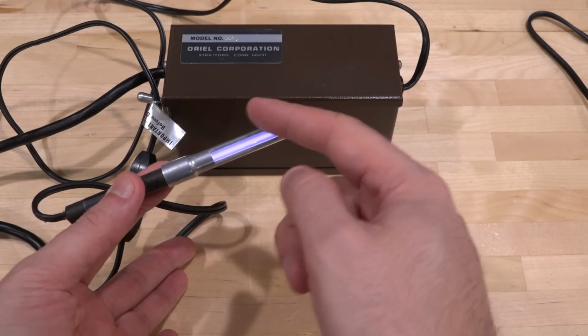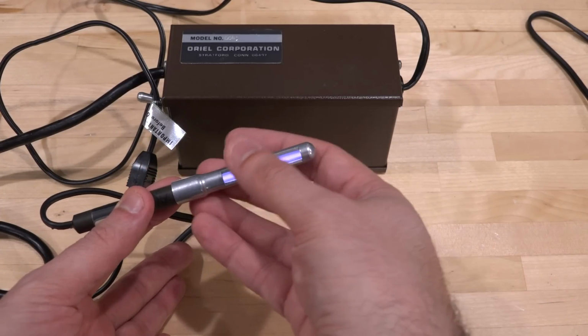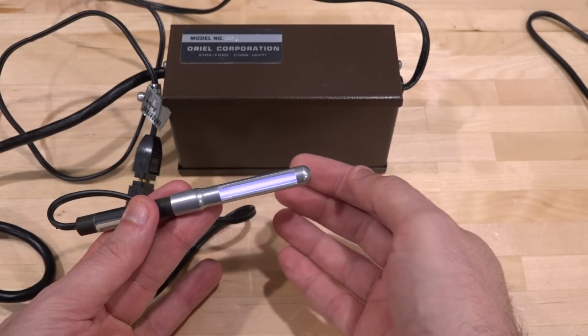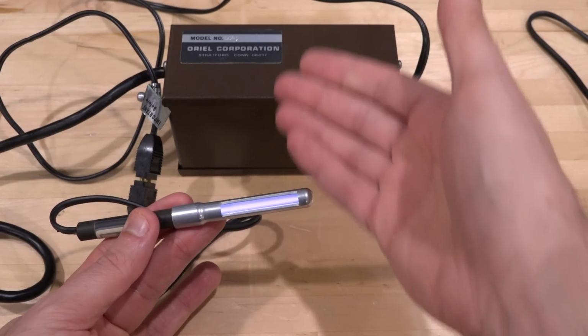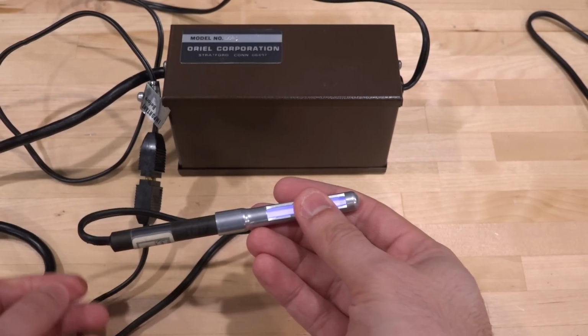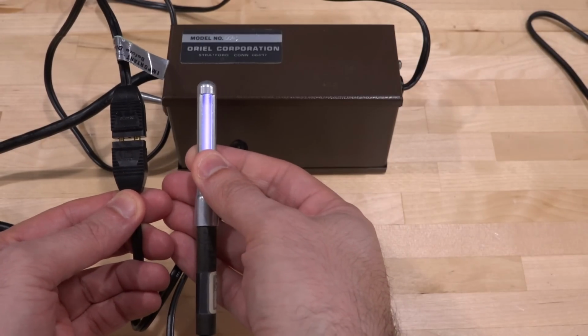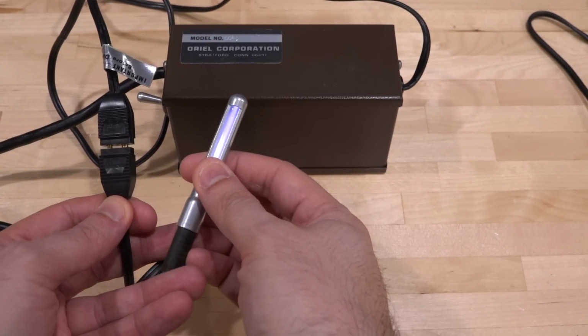And if you apply the same thousands of volts across it under that condition, you would burn a huge amount of power in this tube. So you need to drop the voltage immediately to not destroy the tube. And that's where the self-regulation happens. In fact, we can measure that. We can measure the open circuit voltage, and we can measure it when it's under load and the tube is already lit. And then you can see the difference, which is quite big.